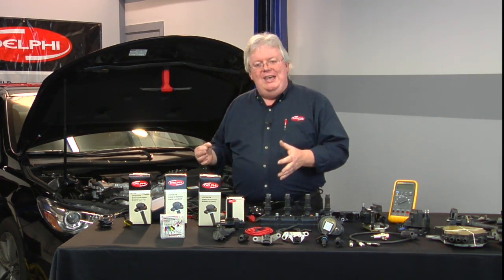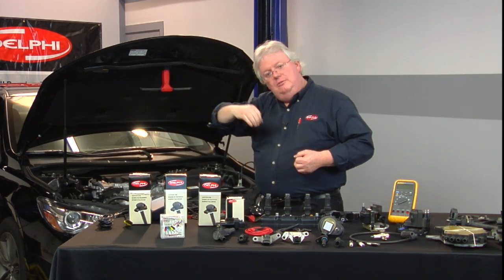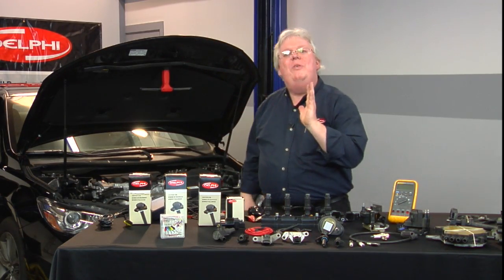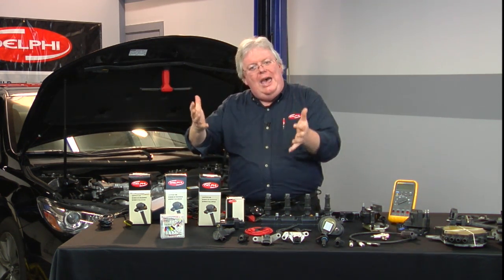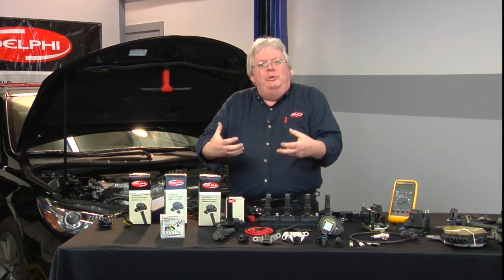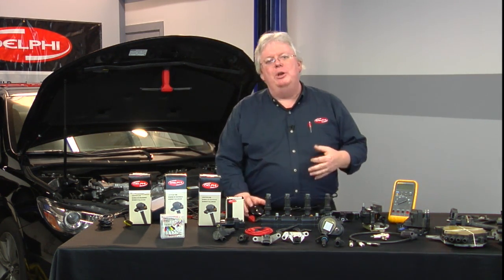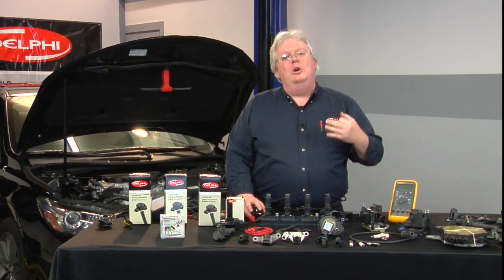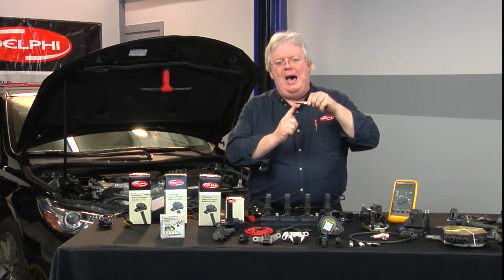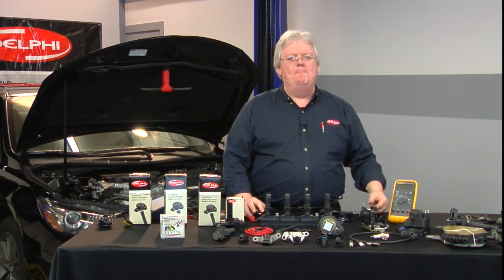We can go for road tests with extended leads going underneath the hood insulation into the car through an open window, with another driver and their tech to do the driving, be your chauffeur, while you use your laptop or your Modus, wherever your scope is built into, and do testing on the road, unless you have a dyno that you can bolt the car down and put a load on. Because as you know, some ignition problems only occur when you're under load and you're stressing out with a lot of kV demand, with a lot of air jam-packed into that air gap, that spark plug.